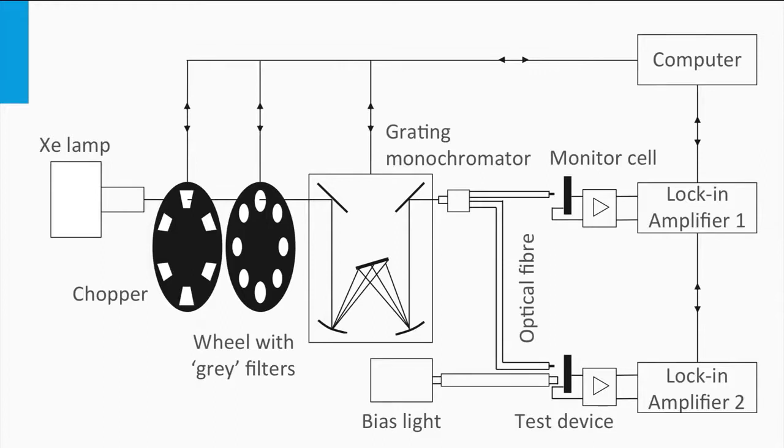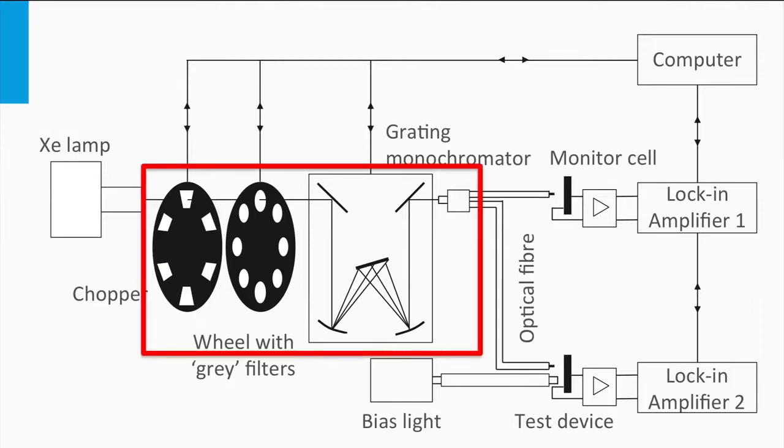In reality, the EQE is always smaller than 100% and its value varies with wavelength. EQE spectra are measured using an EQE setup, also called spectral response measurement. I won't go in detail, but such setup needs a wavelength selective light source, a calibrated light detector and a current meter. A xenon lamp is a standard light source used in EQE setups, as it emits photons in the same spectral range of interest of the solar spectrum. Using filters and a monochromator, only light with a narrow band of photon energies is incident on the solar cell.